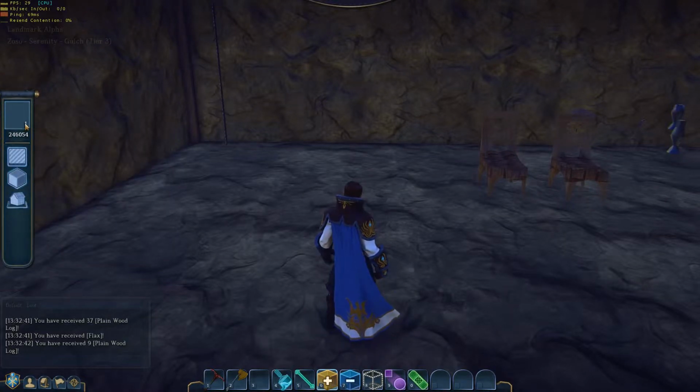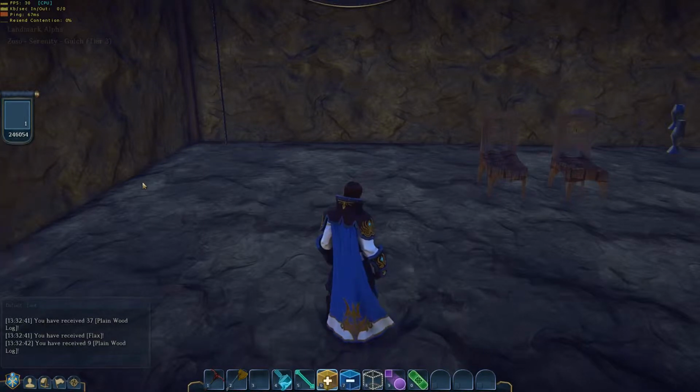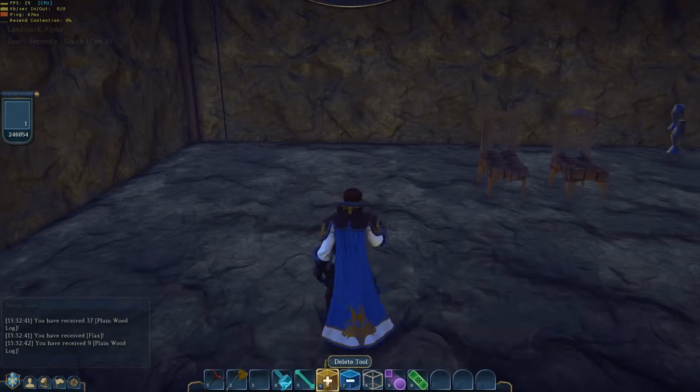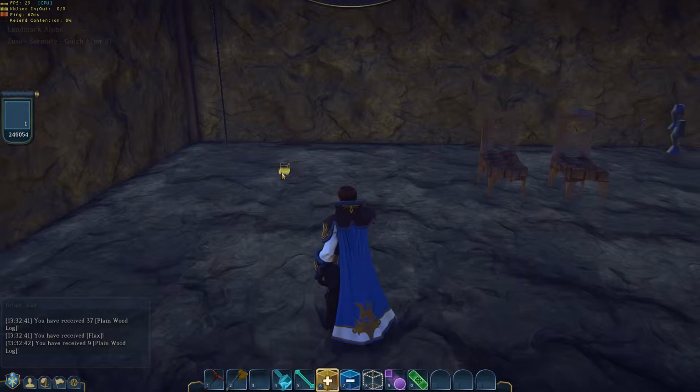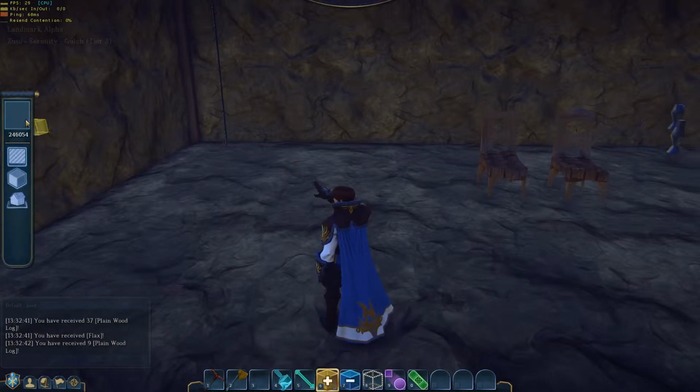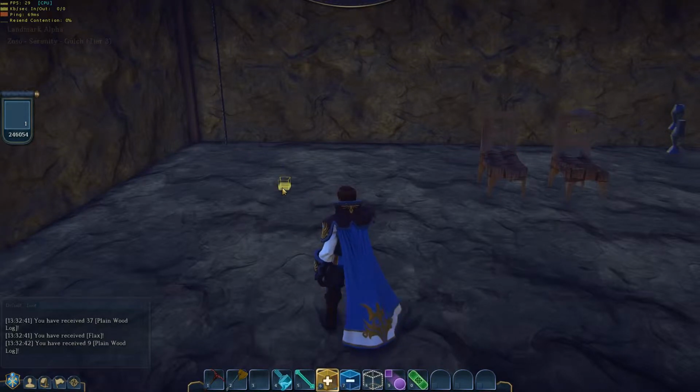It's telling me that I have 246,000 units, right? Voxels, basically, is what it is. So if I then get the add tool out, right? So I've chosen the add tool. Right now I have a 1 voxel add tool, and that's what the 1 here basically is telling me: I need 1 unit to fill up the container I have now. If I make this bigger by scrolling the mouse wheel, it now becomes actually 3 by 3 by 3, which is 27 voxels in volume.